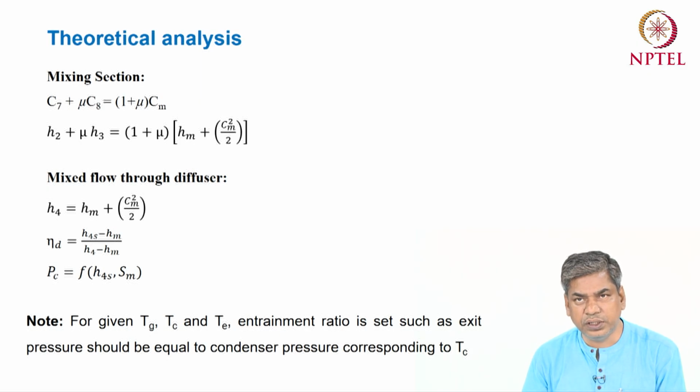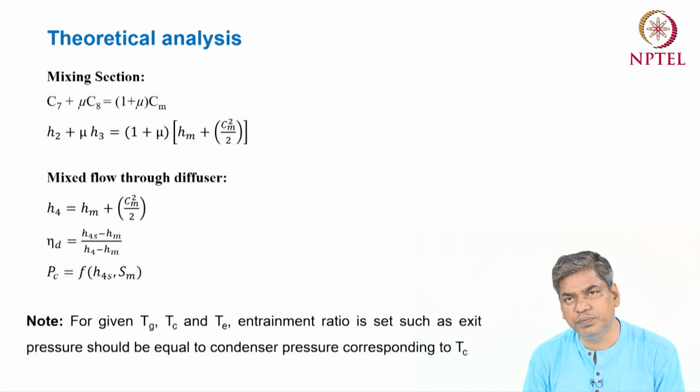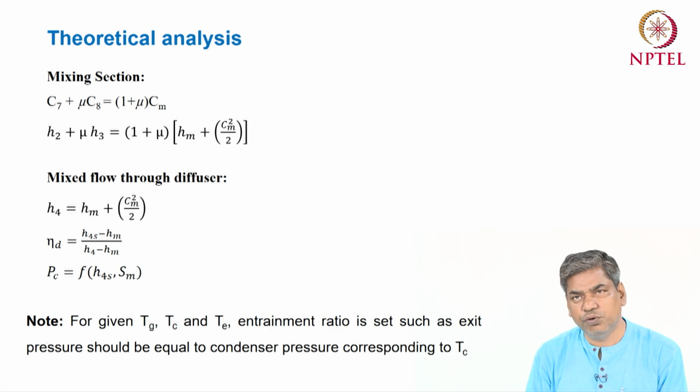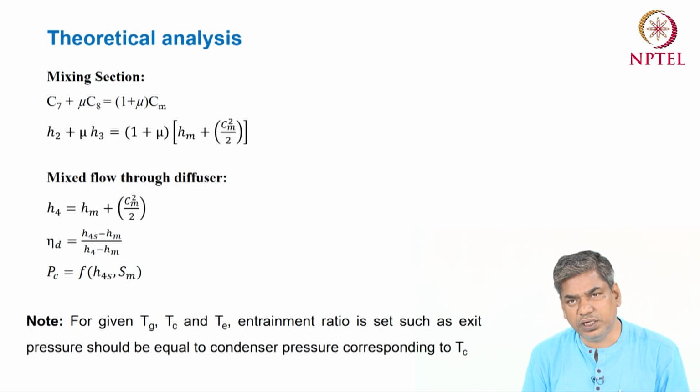But when we are doing the diffuser calculation, for that case also we are basically using the kinetic energy for the conversion to pressure energy. So that's why, if you see the overall scenario, in both cases the outlet condition ultimately will not differ much.